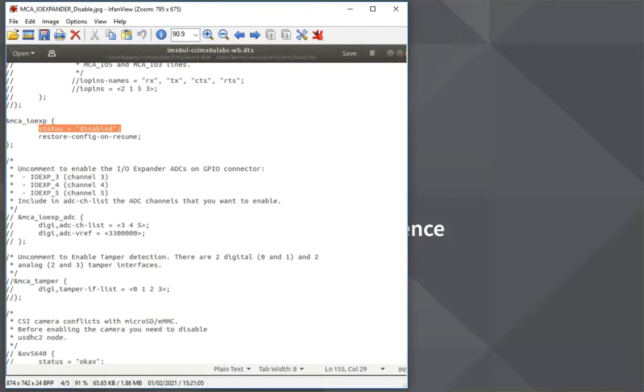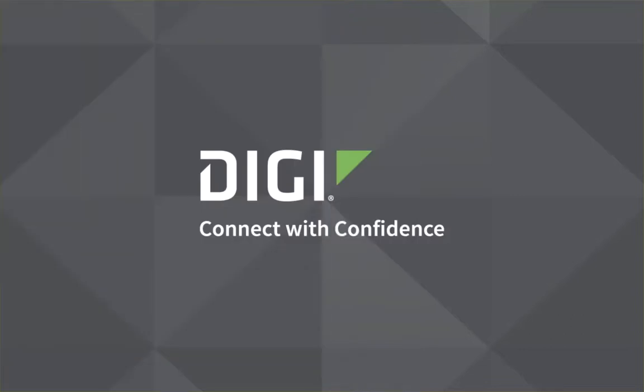In order to get the lowest numbers in the device tree infrastructure, you need to disable the I/O expander section in order to be optimized to the maximum. Of course, after that, you need to rebuild at least the device tree and populate the new device tree on the board.